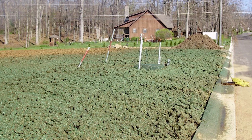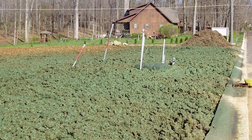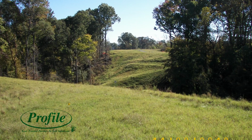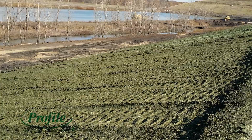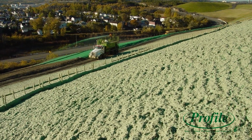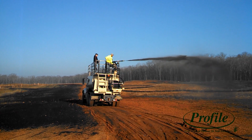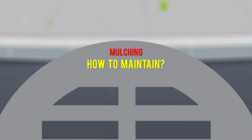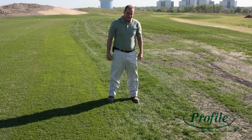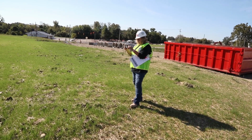How does it work? Prevents erosion by protecting the soil from wind and water impact, provides temporary surface stabilization, prevents soil from crusting, conserves soil moisture, moderates soil temperature, and promotes seed germination and seedling growth. How to install. Apply an anchor mulch as shown in the construction plans. Mulch should have a uniform density of at least 75% over the soil surface. How to maintain. Repair damaged areas, reseed, apply new mulch, and anchor the mulch in place. How to inspect. Inspectors should check for evidence of erosion or movement of mulch.